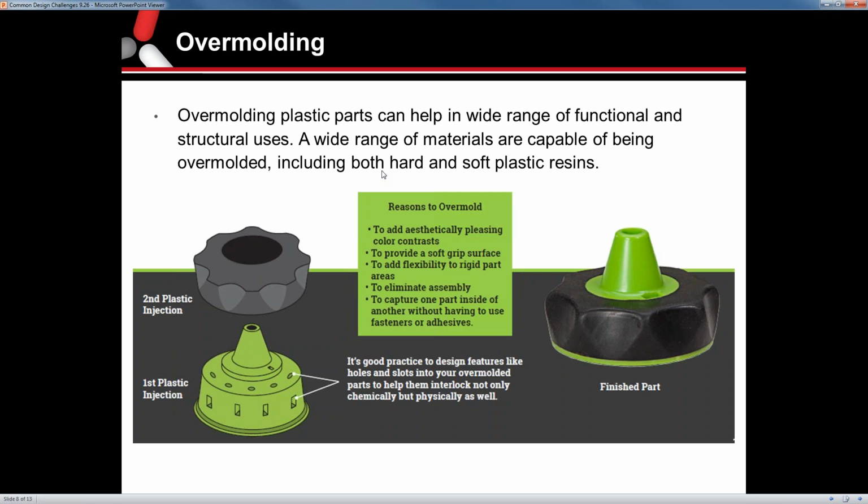All right, looks like we got another question here. How to ensure good flow mixing of fiber impregnated plastic when plastic flows around a feature, specifically a hole? A lot of times, specific filled materials require a certain heat or certain processing to assure that the fibers are embedded in the plastic part. That's definitely something you have to look out for, and when your operators are running these tools, make sure that they're following the guidelines set forth by the material spec sheets.